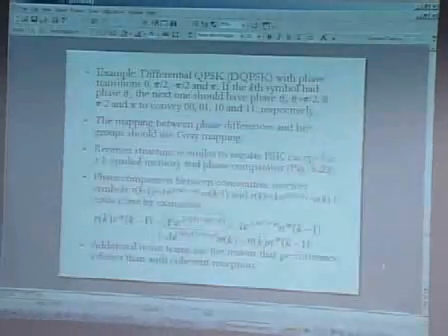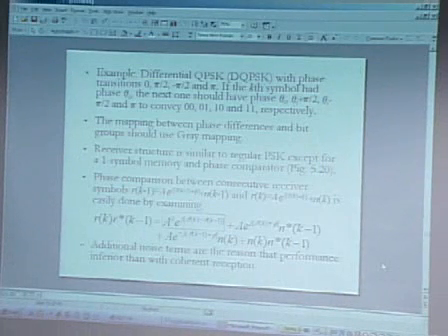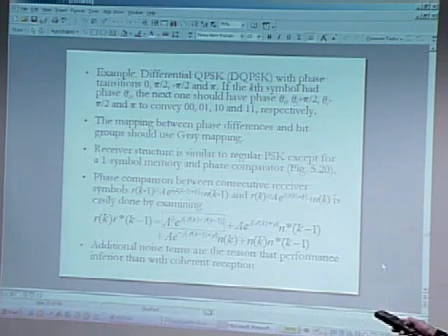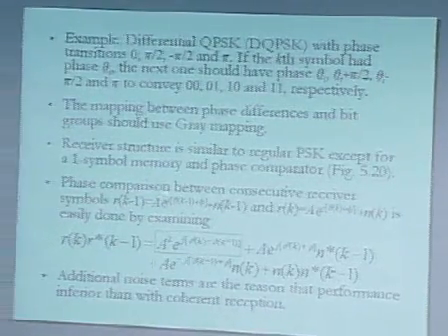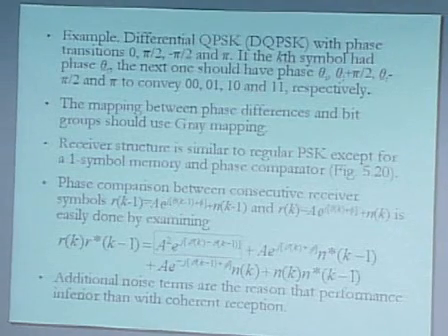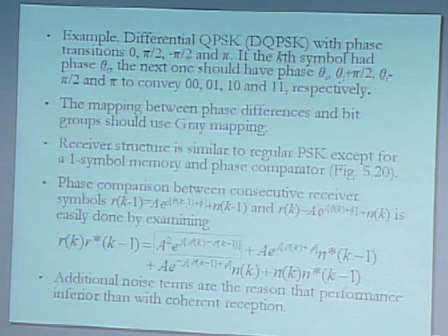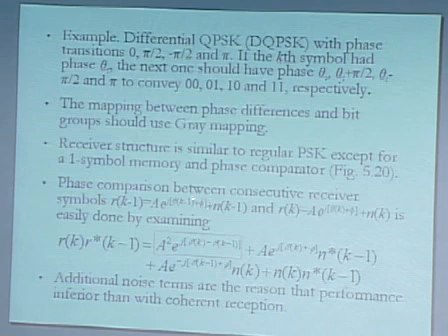So how do we do this comparison? Okay, so let's say that at time k minus 1, we send a symbol that looks like this. It has the amplitude A and phase theta of k minus 1, whatever that is. Okay, so in low-pass notation, the received signal is A times e to the j theta of k minus 1 plus some arbitrary phase, which is the one of the oscillator, which is irrelevant, plus noise, the noise at symbol k minus 1.